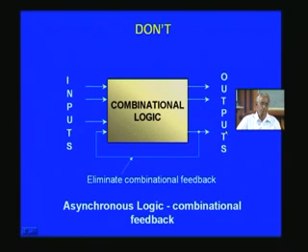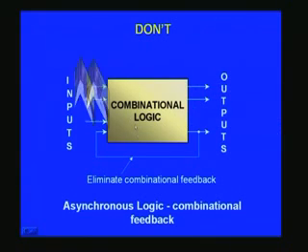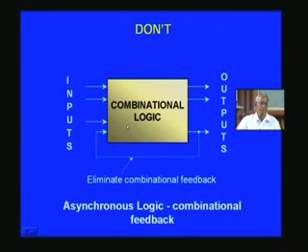When you use the synthesis tool, this is not permitted. It will give a warning or error message as such, and perhaps you can veto that and go along, but ultimately you will end up messing the whole design as such, for the simple reason that your design will not work on the ASIC or FPGA that you have ultimately done. And that's the reason why we should stick to these RTL coding guidelines as such, without which you won't get a working chip as such.